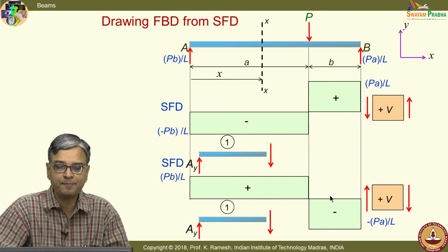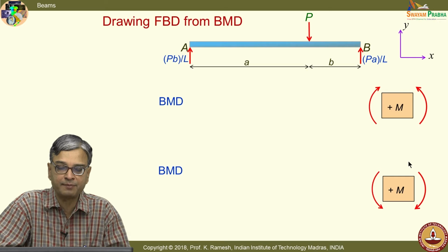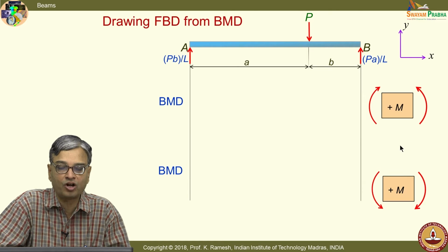We would again repeat it for the convention for the bending moment. I have taken two opposing sign conventions. Here we have taken anti-clockwise moment as positive, here we have taken clockwise moment as negative. So, when I solve the problem and draw the bending moment diagrams, they appear like this.